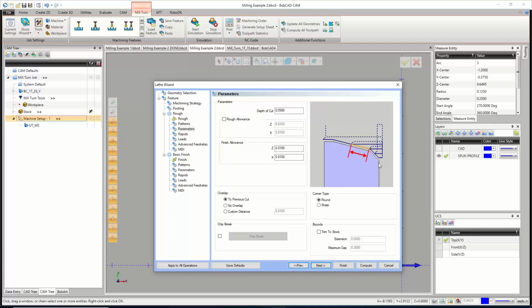So you're kind of doing a semi-finish on your part. You're not going to have a bunch of abrupt, jagged geometry here. Compared to that, if you were just doing a no overlap where it just runs in and leaves, you'd leave the radius of your tool every time. So this will just give you a better blend before your finish tool comes in.